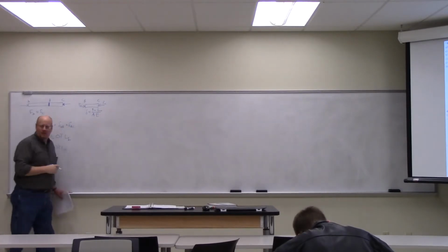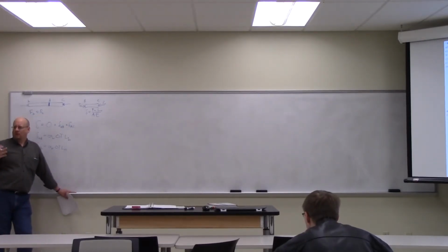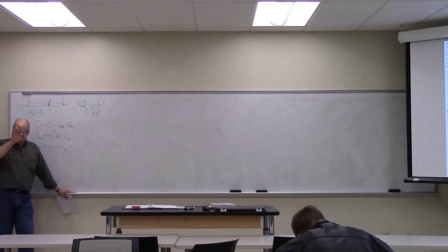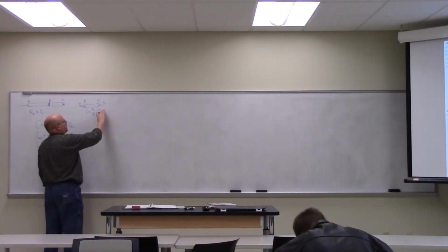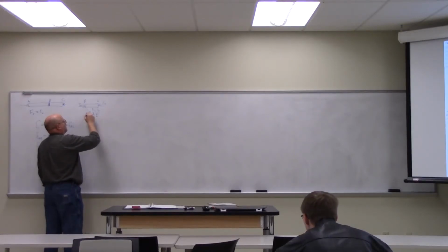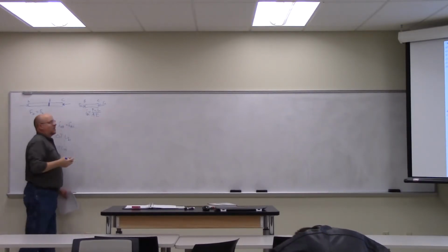That's fine. We'll just leave it as the initial length. They don't differentiate. Once you get into engineering stress, they no longer differentiate initial and final length. Here we're dealing with engineering stress and strain. The length is always the initial length. Okay. So, but the thing is, I need to label that, which length of what? What length has to go in there?